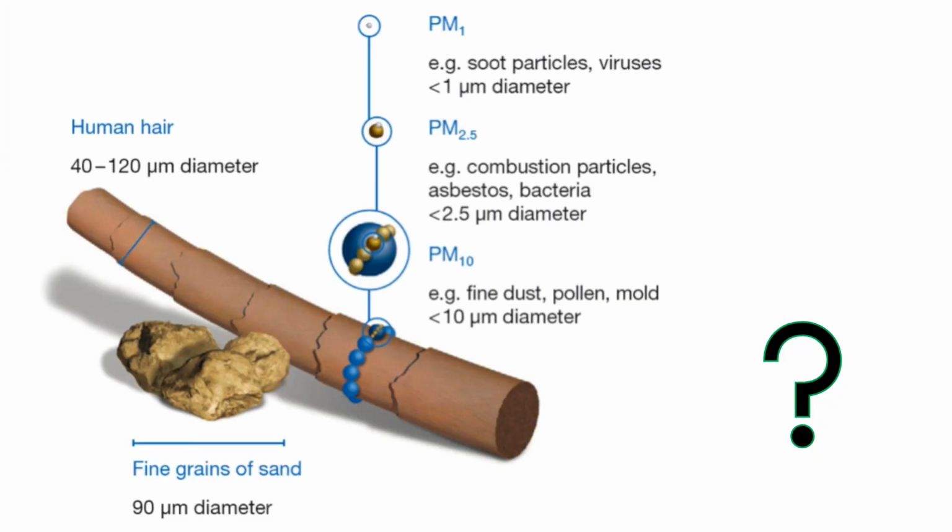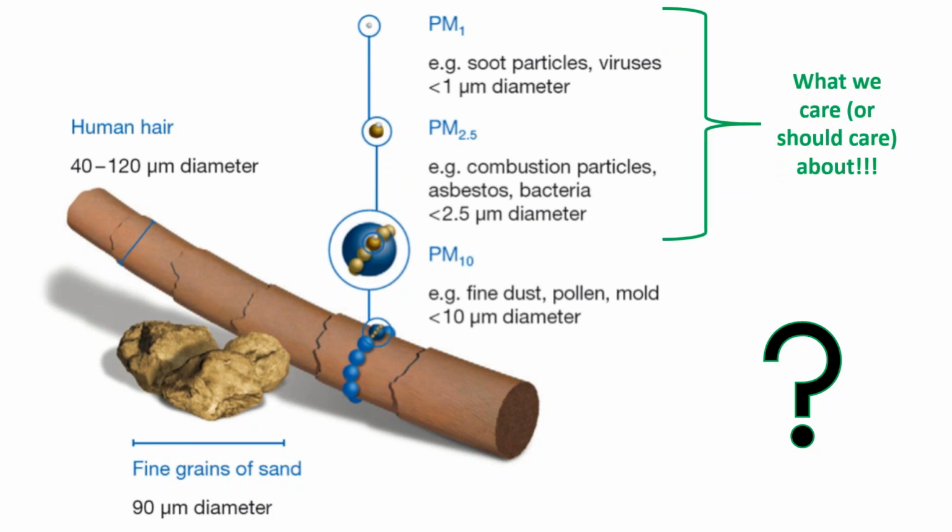So what kind of particle size are we talking about? And again, we're just going to glaze over this. We're not going to dive into it too far, but really what we're interested in is what we call PM10 and smaller. That's particulate matter 10 micron and smaller. We're not interested in larger than that, especially when we're dealing with HEPA filtration, because we want the HEPA filter really concentrating on these small particles that general filtration either struggles with or cannot do.